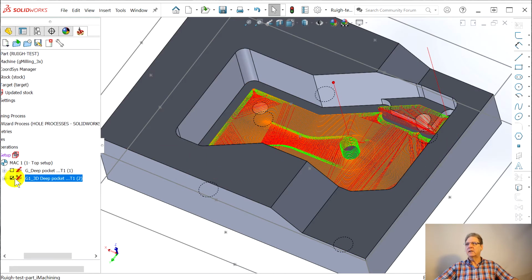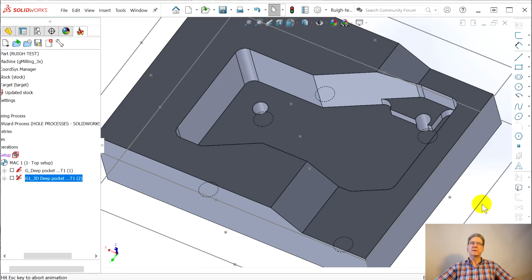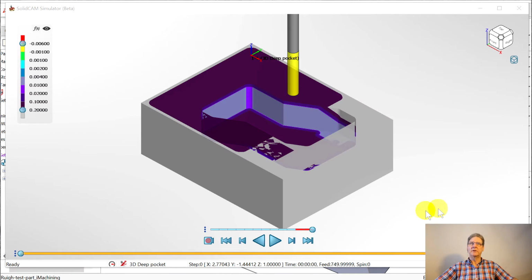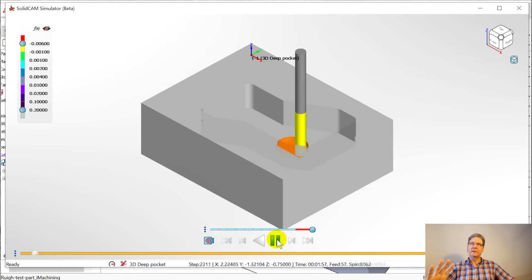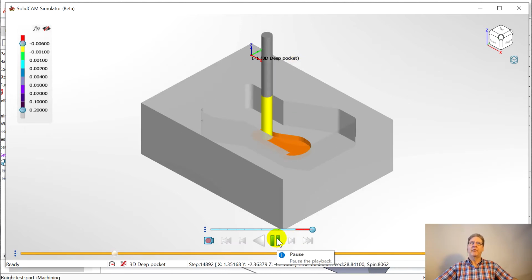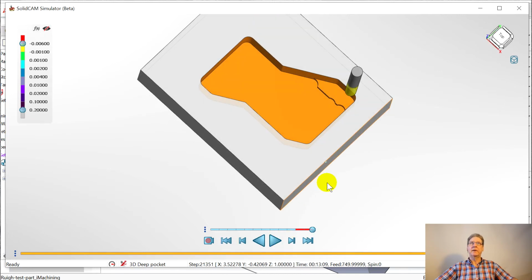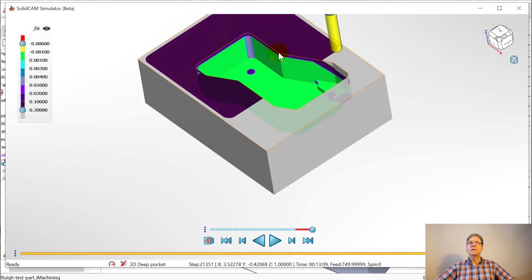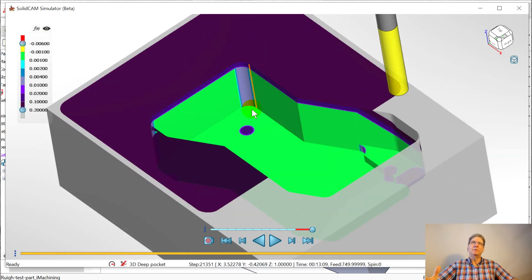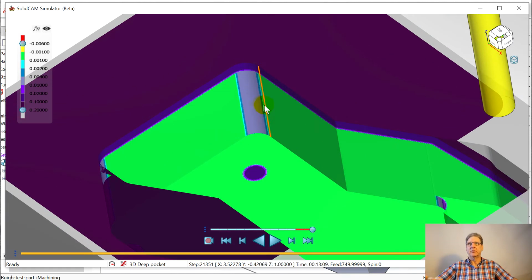Let's delete, go here, do our fantastic simulator. I do love this simulator. Take the compare function off, and now you'll see, I think we zeroed everything, right? We didn't ask for a stock allowance on anything. So it's doing its thing. Well, that was quicker than before. That's interesting, isn't it? Okay, so it leaves the same stock, and I guess I was first very upset by this, but I was like, okay, it's roughing, and nobody thinks roughing should go to exact.